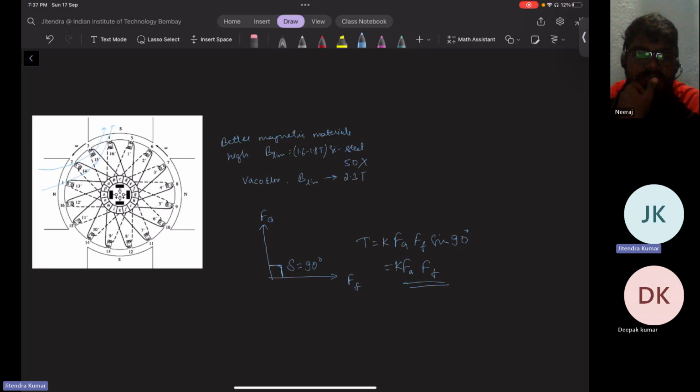Let me break it into very simple terms. You are breaking your stator MMF into two parts, active and reactive. The active portion is responsible for generating the torque and essentially your output power, and the reactive portion is responsible for creating the rated value of magnetic flux in the machine. Both works are carried out by the stator armature winding in the case of an induction machine.